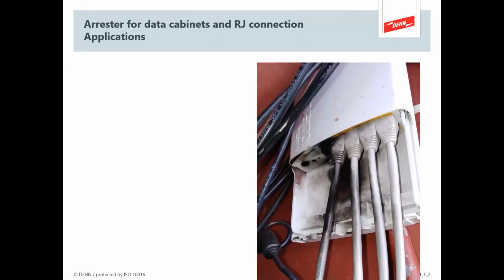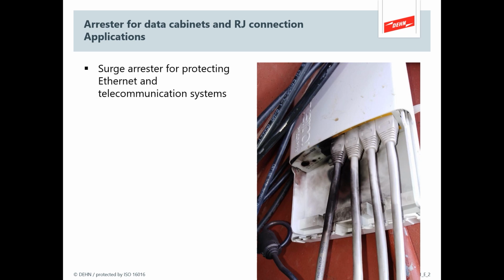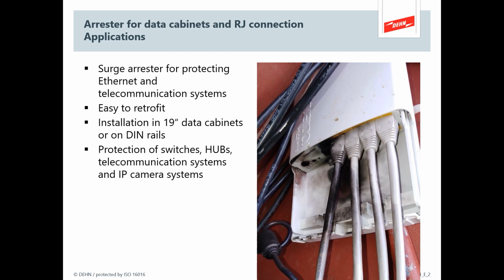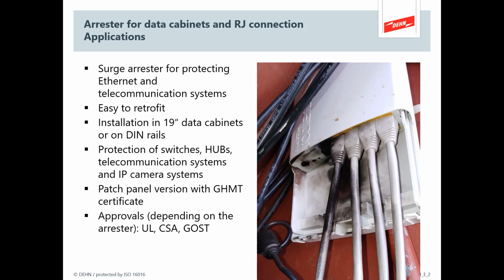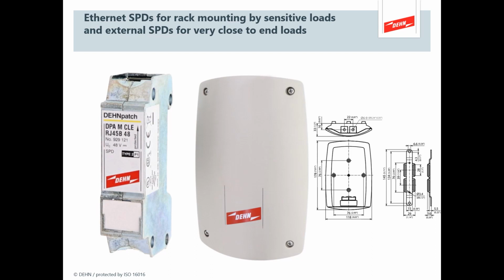It's very important to consider this. As you can see, Ethernet cables are susceptible to surge, especially from external components. So you need these SPDs to protect telecom systems or any other sort of IT arrangement. They're easy to fit. They're just a plug-in arrangement. They can fit into data cabinets or on DIN rails, and they would protect all sorts of external equipment. And there are various approvals and standards associated with those devices.